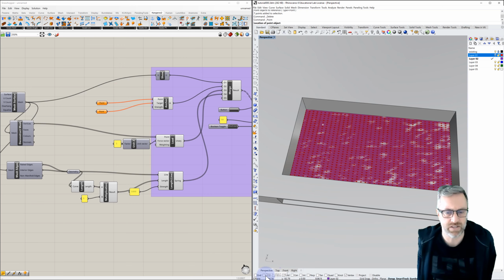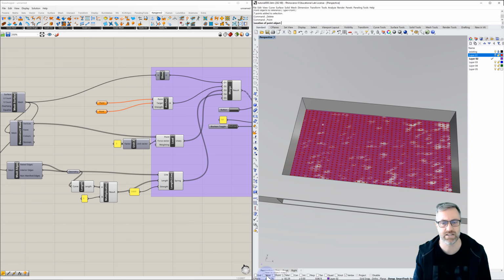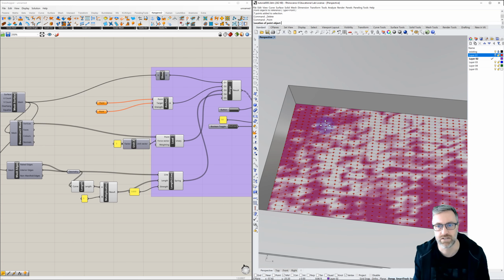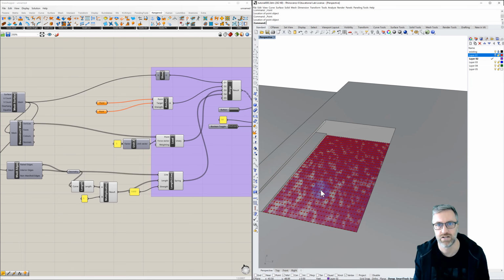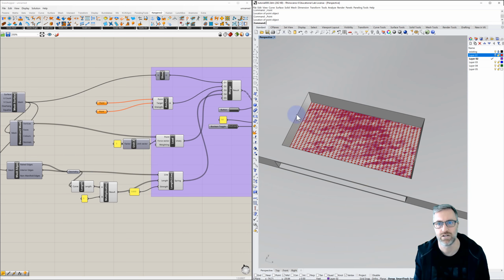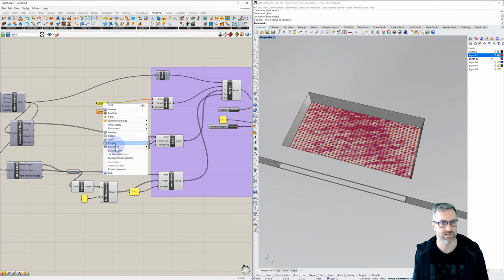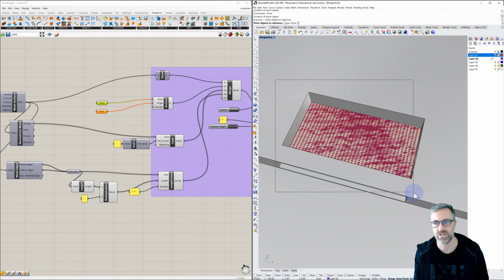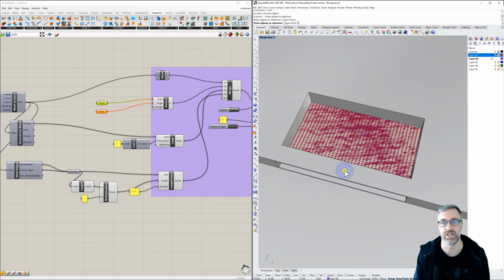And even sometimes when I look at students' computers, sometimes near is selected. You should never, never, never have near as one of your snaps. So let's make sure that we're only snapping the vertex. I think I'm making points now, although I don't see them. All right, so there are a few points there. So now we'll make sure that's not selected. We'll go to the point container, set multiple points. We should be able to window. I selected the points, remember to hit enter.